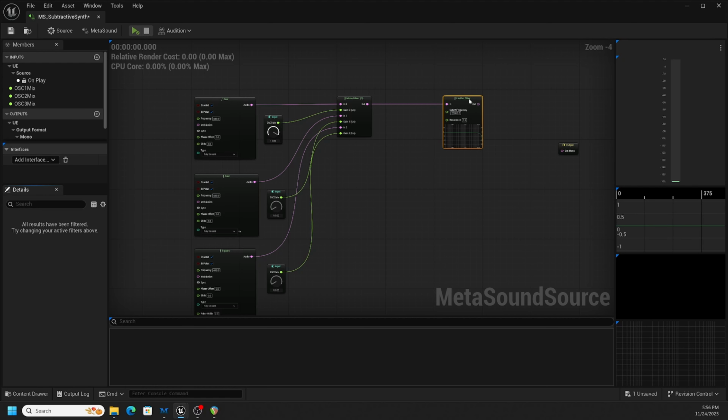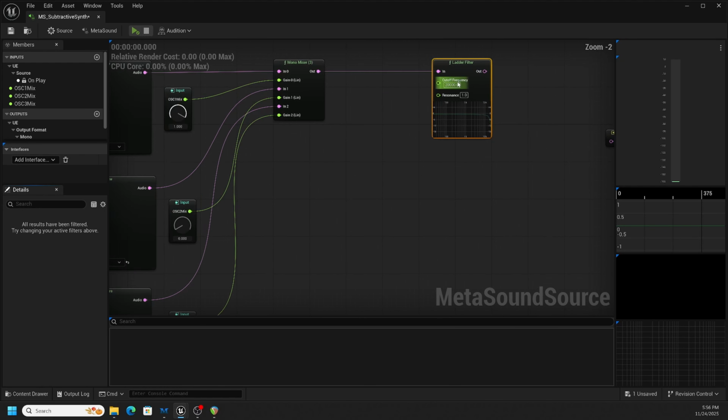And there we go. We're right back to where that demonstration patch was. So cutoff frequency at 20,000 hertz is, there's no filter at all. It's not doing anything because that's the highest frequency that we can hear as humans. Now, in analog synthesis, and in our case, since we're emulating this kind of analog synthesis approach, there isn't a lot going on at 20K. There's not a lot going on at 15K.